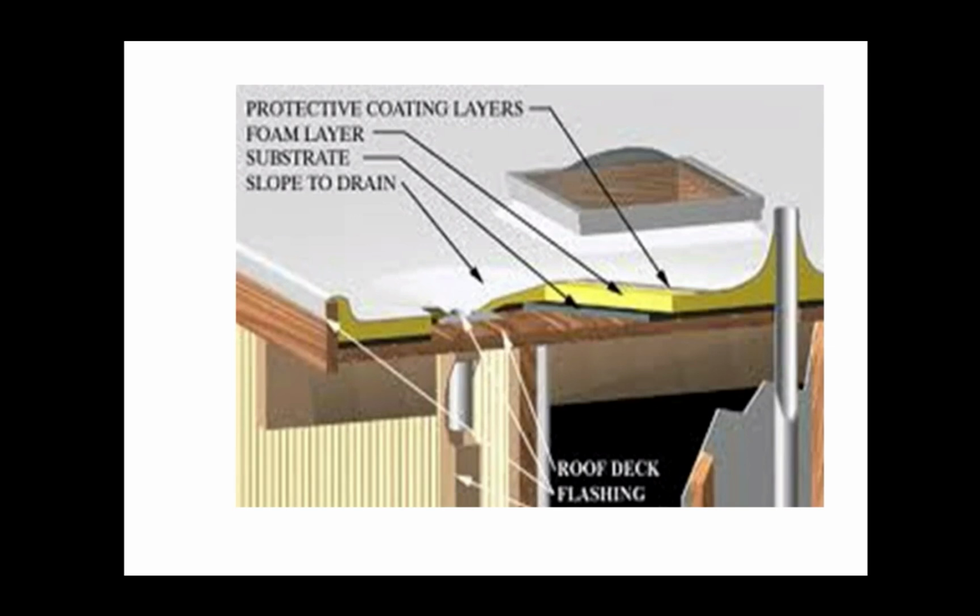Generally, the roofing membrane will be linked to a higher elevation level on the exterior perimeter of your roof, and that's to give it a place to latch onto and to connect. All right. So you can see how the details are formed there with that foam layer of insulation and then the protective coating on top of it.